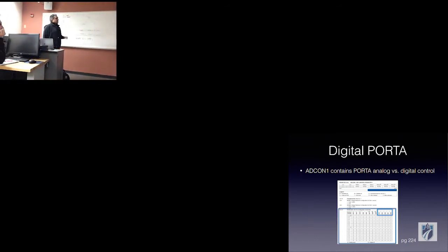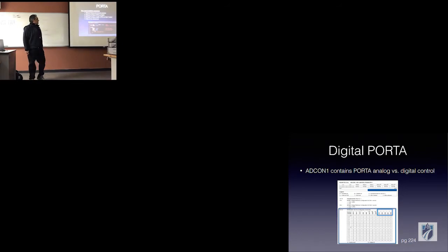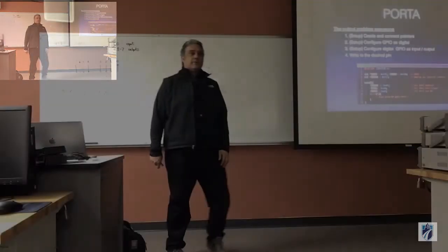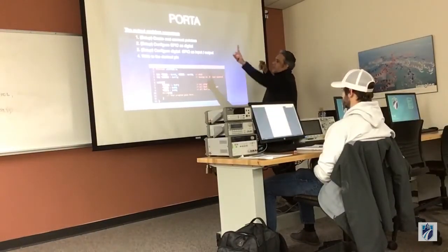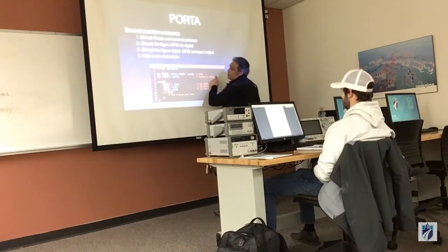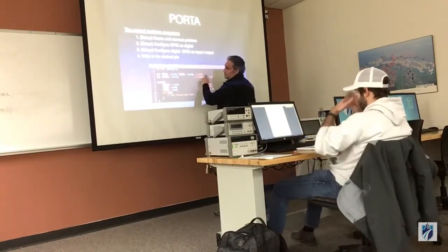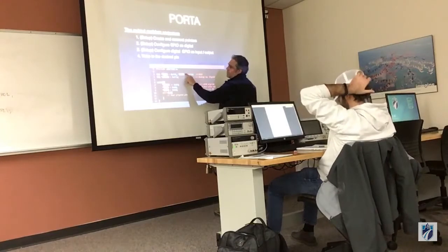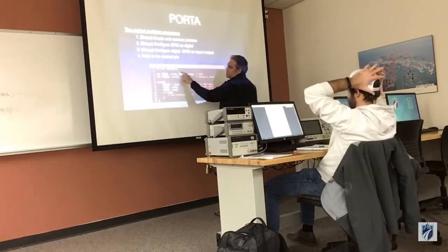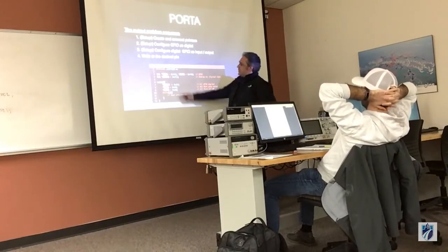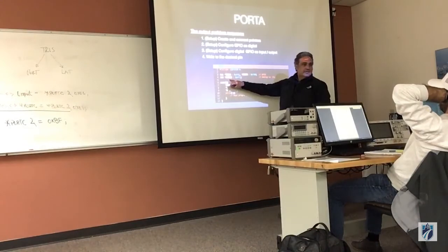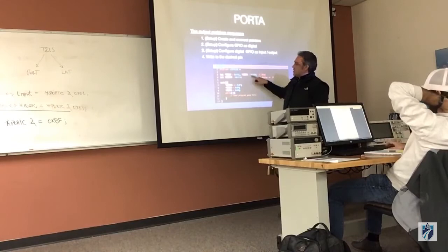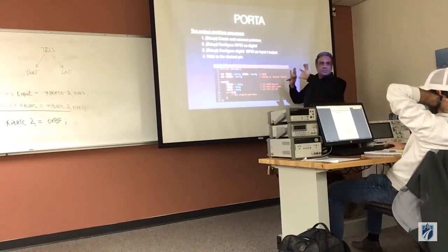All right. So here we go. Here's the software. So I'm going to be going back and forth. I want you to see a couple of things. Number one. When you take a look at this bit masking, this bit creation up here, this is nothing more than I want to create a bit connection to my circuits. So I have the TRISA circuit, the PORTA circuit, and the ADCON circuit. Right? This is the part that's green. Then I go with the TRIS. Then you go with the port. I'm just creating a connection.